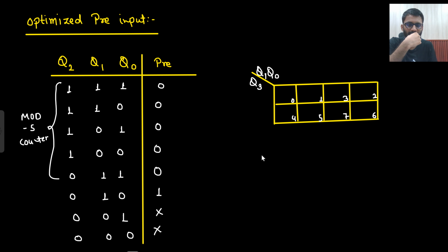So at here, this term is not 3, sorry, this term is 2. So at 2 my pre-output should be 1, and 0 and 1 are my don't care. Here you are 0, here you are 1, 0 0 0 1 1 1 1 0. Right? 2 is 1 and 0 and 1 are don't care. So I can see that this is what I am getting. So this don't care I am using now.